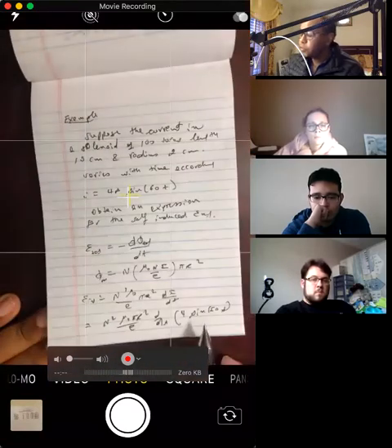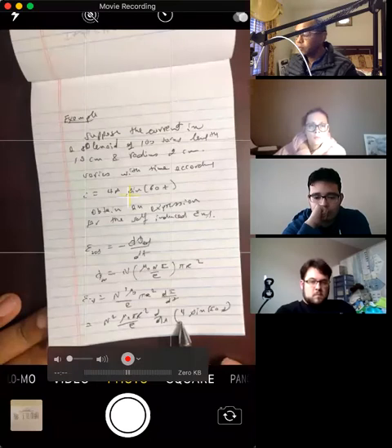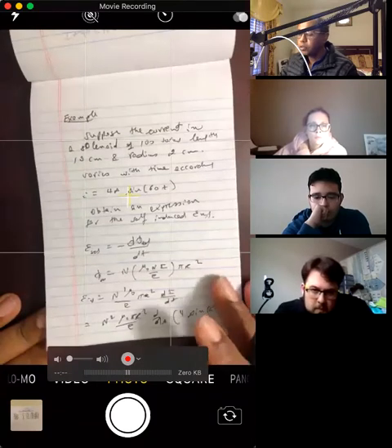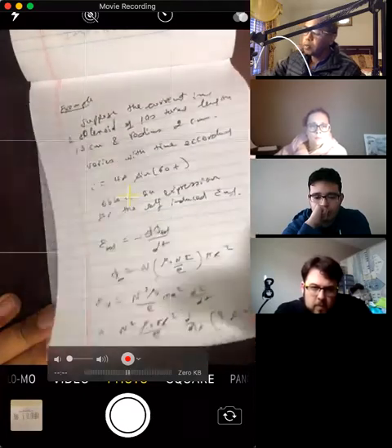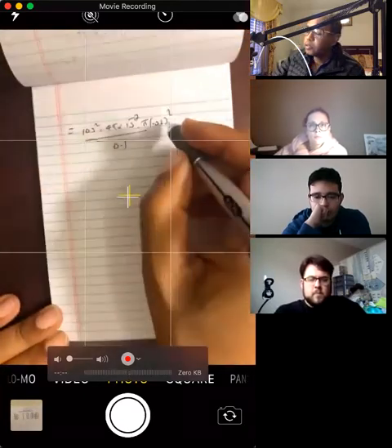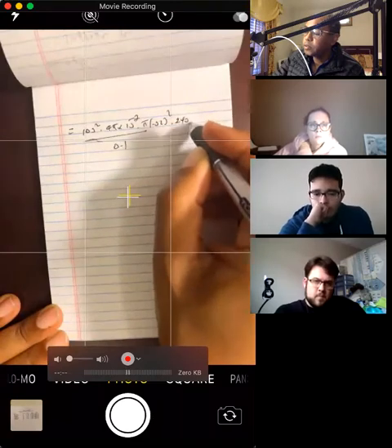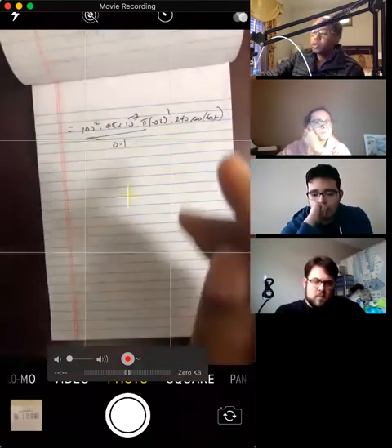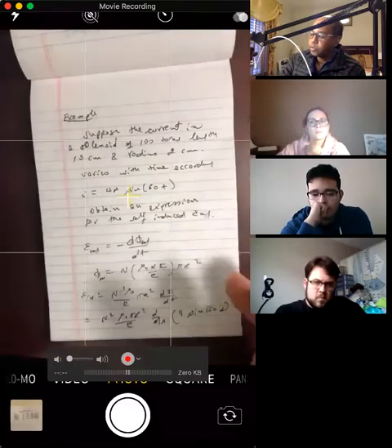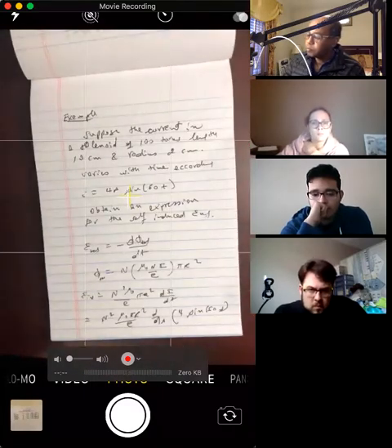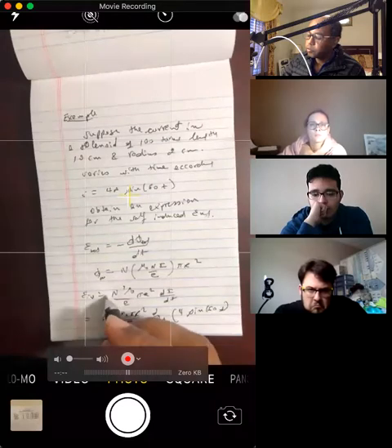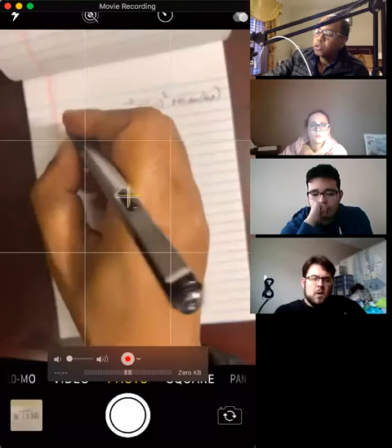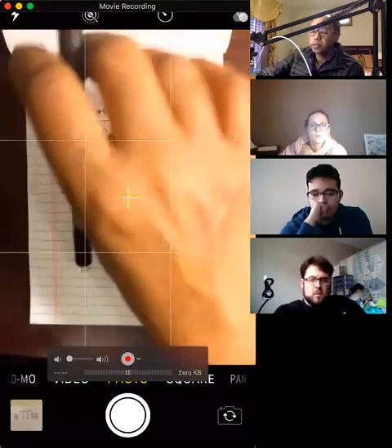How about the derivative of this? This would be 4 times 60, 240, right? The derivative of this one. So it'll be 240 times cosine of 60t. Well, I think I forgot the negative. There's a negative over here, the derivative has a negative. Negative, all right. So that's how the voltage across the coil is going to change.